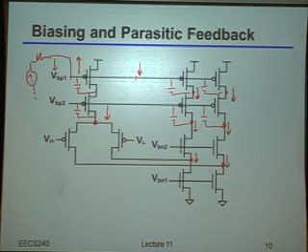So what's the number one thing you always have to check with a feedback loop? Yeah, stability. Even though this is negative feedback, if I have enough poles or closely spaced enough poles in that feedback loop, it may not actually be that stable, or maybe marginally stable. So by the way, what would be really bad if that feedback loop was indeed unstable? What would happen to the circuit? How would it behave?